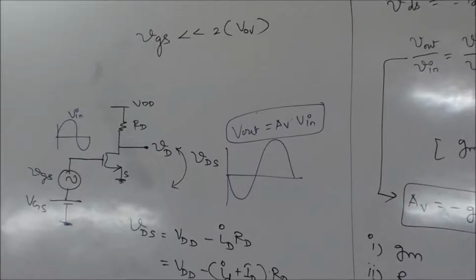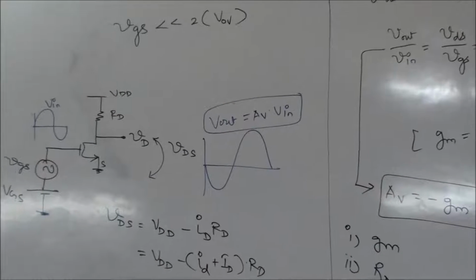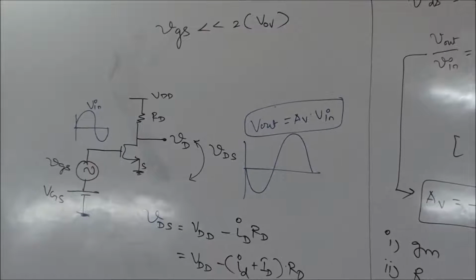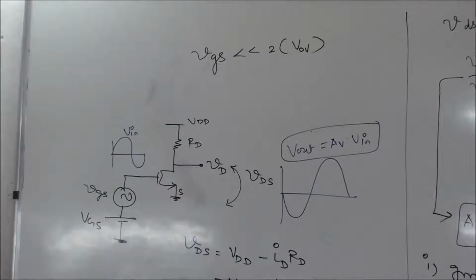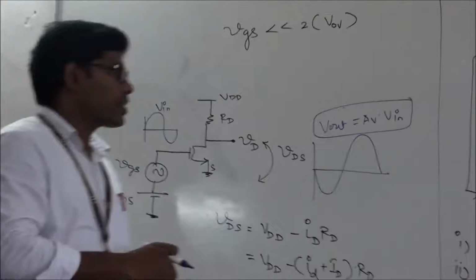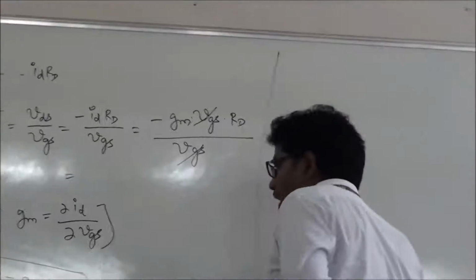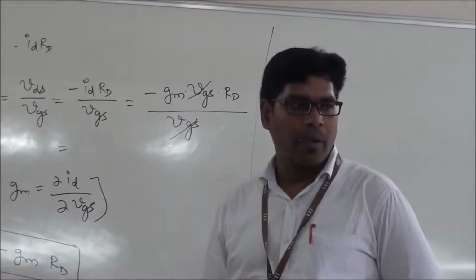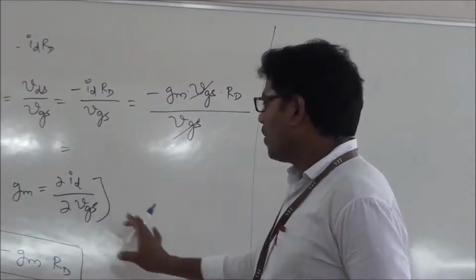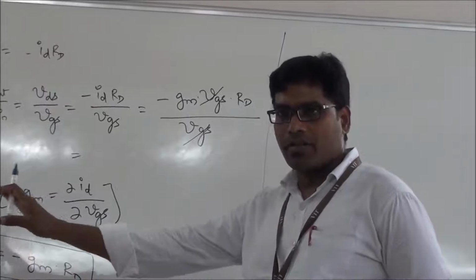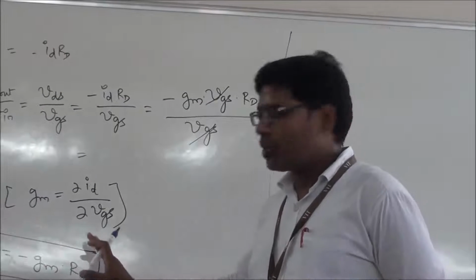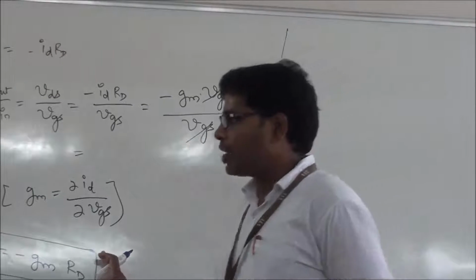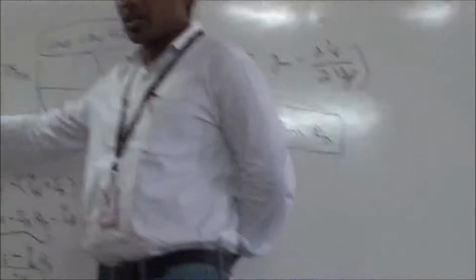The same circuit, if it is going to be in a digital network, can be called an inverter. How? Very simply, take this. In analog, I call this an amplifier, a common source amplifier, where whenever I give some input V in, the output is going to be amplified by this gain and you get the output. Only thing you need to make sure is VGS is greater than VT, the threshold voltage of the device.